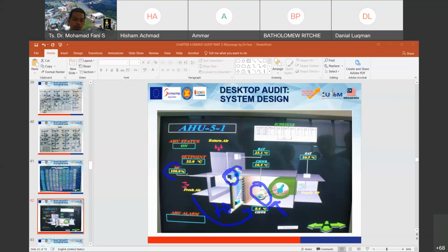If you monitor it, you can reduce the actuator valve opening percentage. The system will react something like this: when the room temperature is near or a bit over the set point and achieves 22, suddenly the actuator valve will be closed and maintain the condition of the flow rate for the chill water and the temperature of the supply air side.